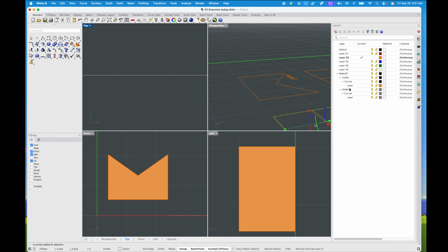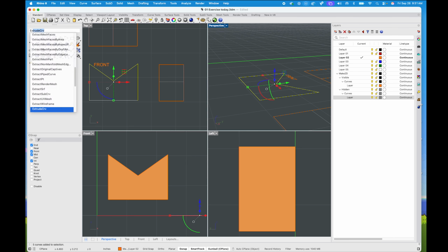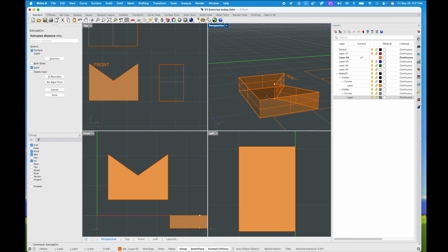In fact, you'll see that it actually makes its own layer called hidden layers. So I can turn those off, and you can definitely tell that they're hidden, or they should be a dashed line. There you go. There's the answer to the entire thing. We can make the object, and we can go back and forth between the objects. I can even take this object, extrude an inch, and rotate it by holding shift. It'll be a perfect 90 degrees. And I can literally remake the object again, proving that these two objects are congruent. They literally come from each other.